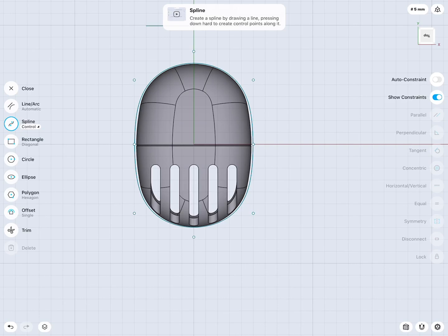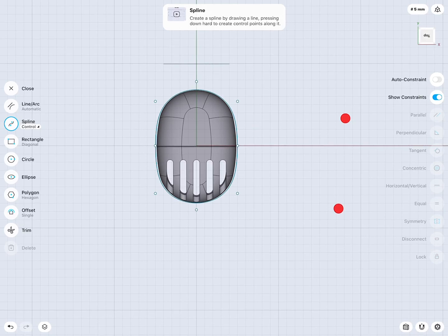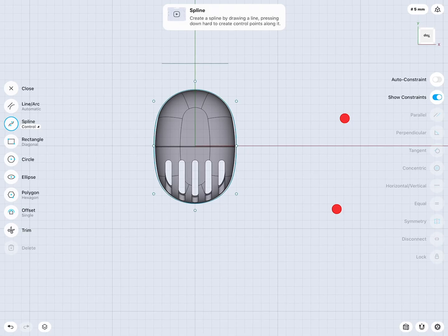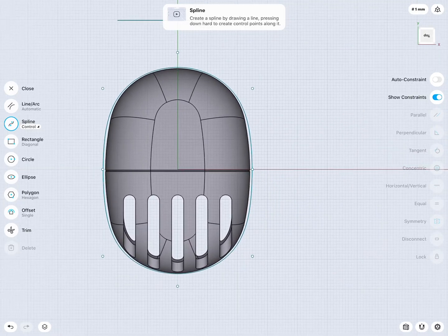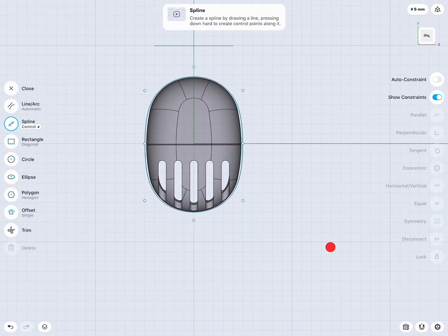I also drew everything further from the outside, so the grid is more coarse, which makes it easier to put down all the CV points evenly, left and right, in terms of symmetry. And then when we move everything in more detail, we can zoom in and use the move command to do this more precisely. Okay, very nice.